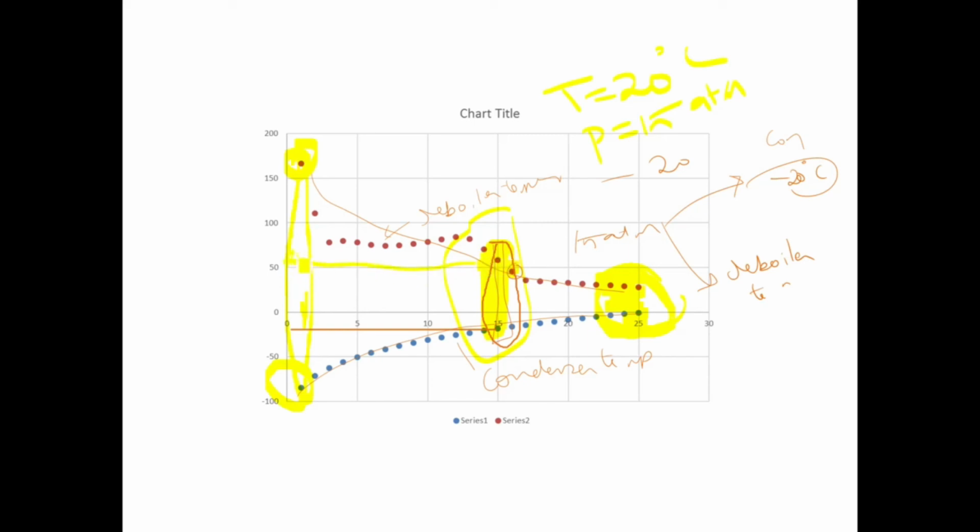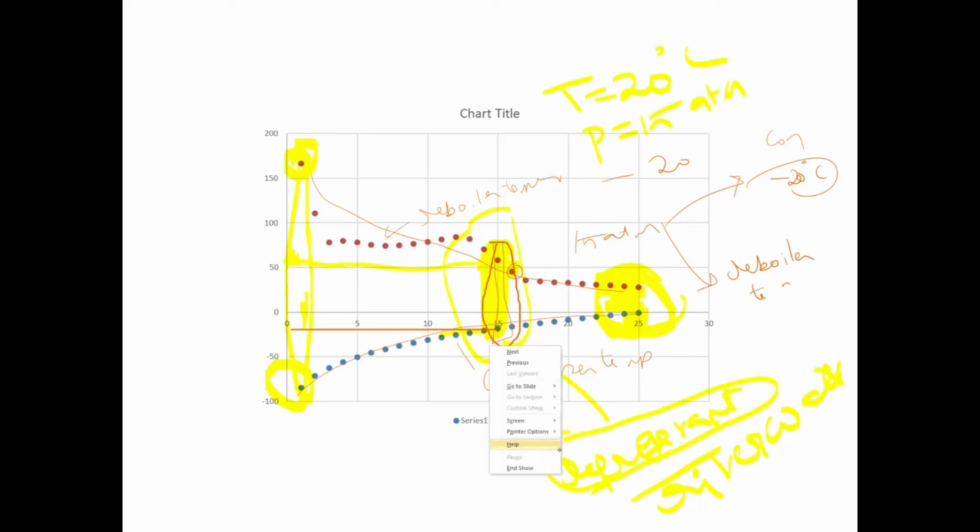It will change once we add the distillation column, in the reboiler, and then around minus 26 in the condenser. Obviously we need to use some refrigerant instead of river water. So refrigerant instead of river water. Okay, so we need this fluid in order to condense the streams. So keep these things in mind.